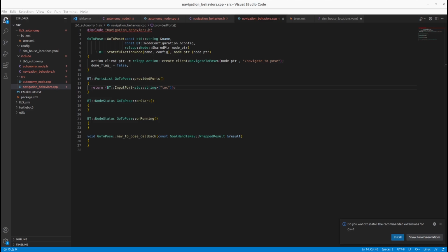Okay, so the idea is your behavior tree will be ticked every 500 milliseconds once it is created. Each node will be ticked from left to right. It is a sequence node, and I hope you know what the sequence node is. The first action node needs to be successful for it to go to the second node, and then third and fourth. Again, if you don't understand this, please check out my series on behavior trees.